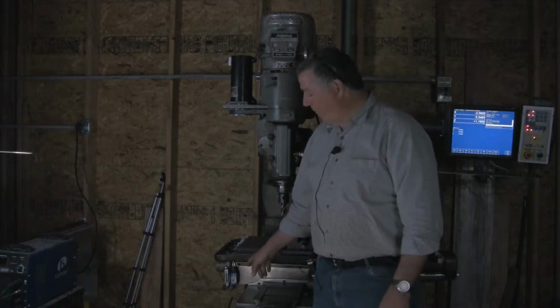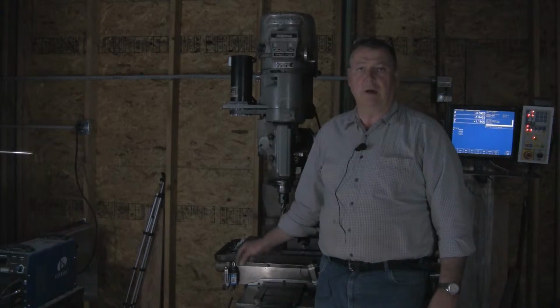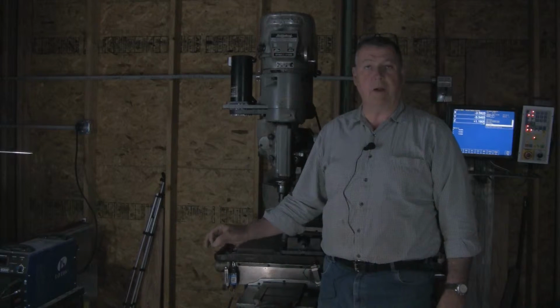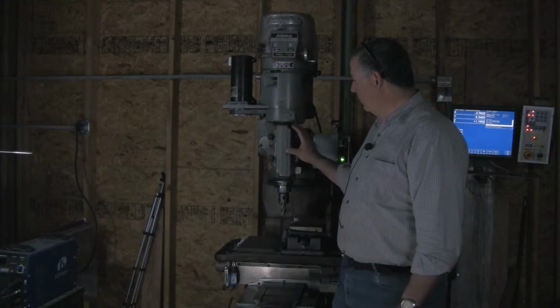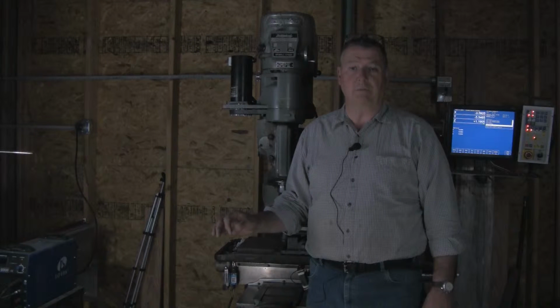Hi. Today we're going to talk about home and limit switches. You may recall from the first video that I disabled X and Y in the homing and I was using software limits only. I have been able to install a new X home and limit maximum switch for the X axis. I still do not have a Y positive limit switch, but I do have the Y negative limit switch. So with that and the two of them that are functioning on the Z axis, we'll be able to go ahead and set up the homing system on this machine.